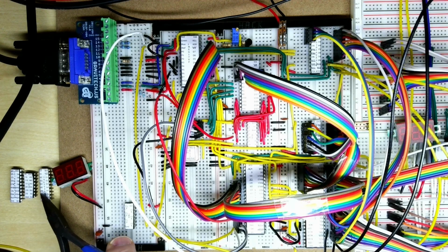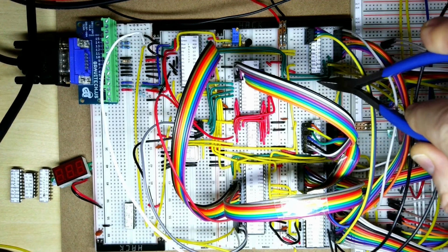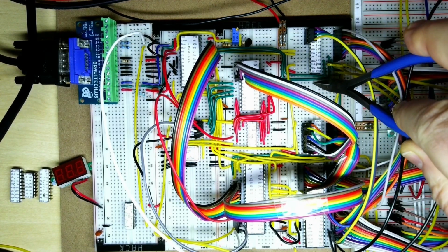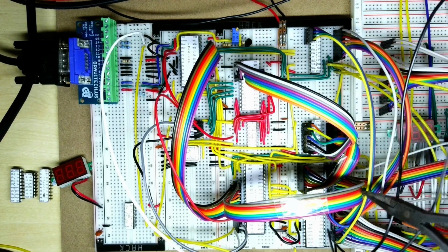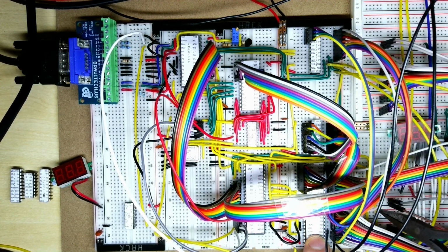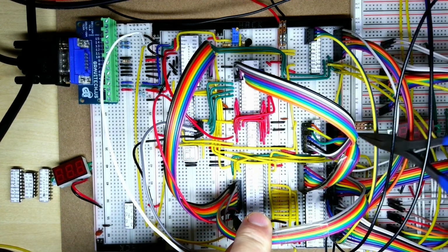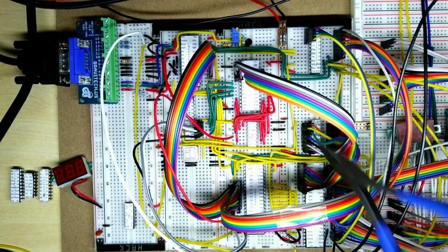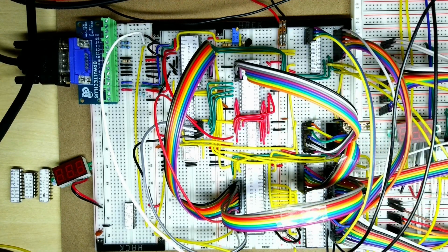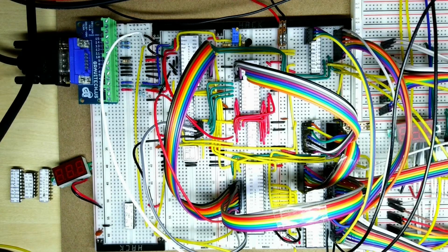So here are the chips we need to add. This is the buffer, and that's going to be going between these two chips here. Hopefully we've left enough space in the last video to add that in. It will also need to be wired into the data bus here, so we might need to find some spare data bus lines that we can wire that into. There are only 2 signals coming from there, one to horizontal sync and the other to the video output, which will wire up to probably the output of the shift register for the moment.